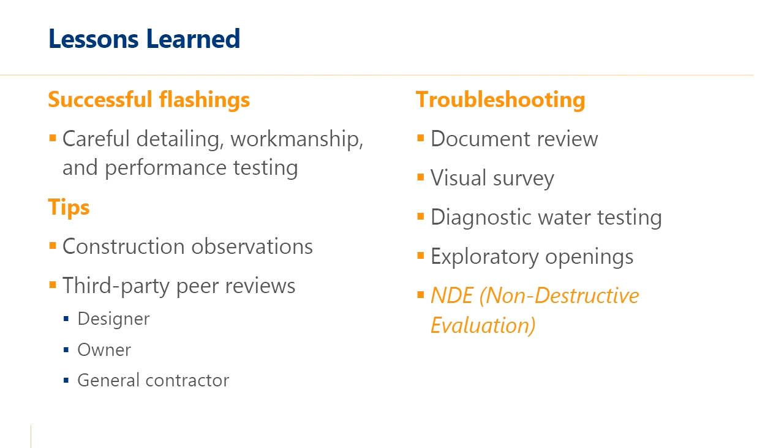Another tip to take away to achieve successful flashings is to have construction observations during the work. So whether that's by having a manufacturer's rep come out, or the architect of record, or a third-party testing inspection agency, they can verify that the flashings are being installed in accordance with the drawings and the manufacturer's recommendations to provide some of that QA/QC during the work.